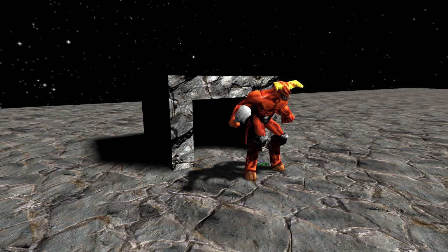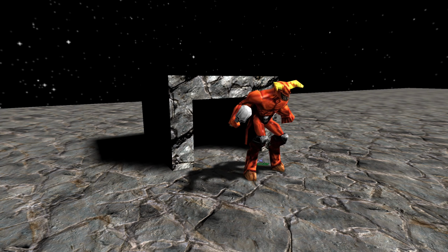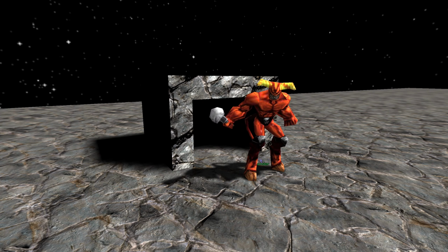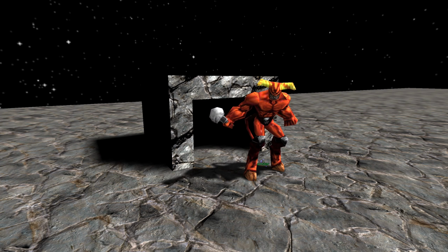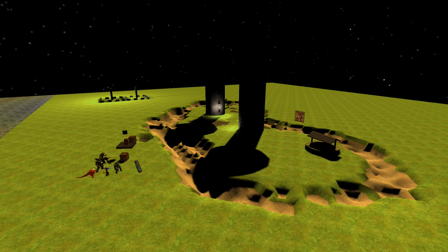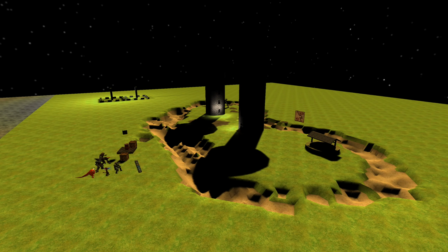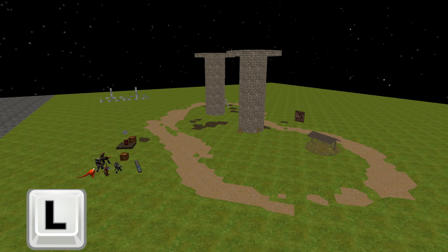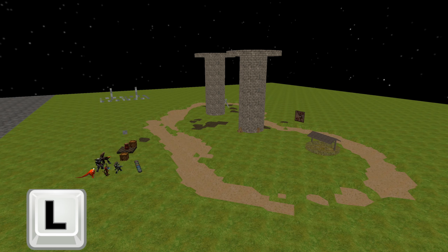On a space map, we might set sky and fog color to black, set the fog's falloff to an insanely huge value, and make the ambient color all black too, while making the sunlight somewhat more intense by increasing its scale. If we want to get back to modeling and don't want to see any light, we can, while in edit mode, press L to toggle the full bright mode on and off. This will hide and show all light maps.